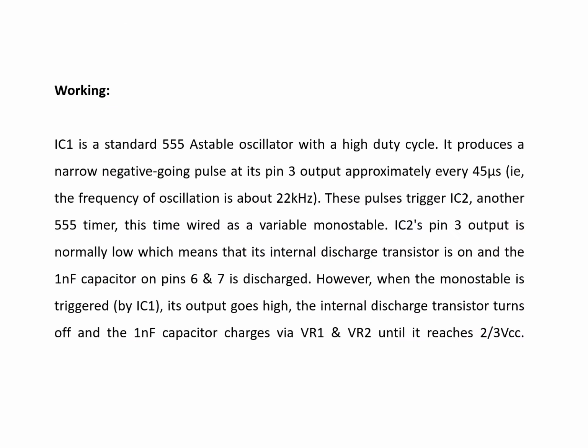So this is how the circuit is working, and the lamp is controlled through the MOSFET driver. Instead of MOSFET, we can use some other switching devices also, such as IGBT, SCR and so on.